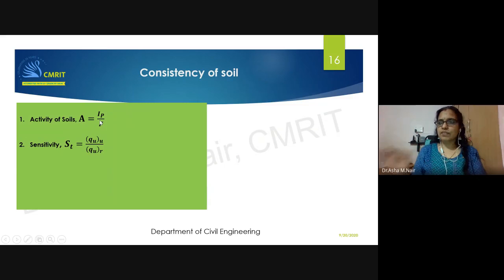Activity also, today we have done 2 problems based on activity. So please don't ignore these topics, because there is nothing so difficult in this, but please ensure that you are aware of all these things. So activity is equal to IP by F. And sensitivity also we have not seen, but I am telling you, you are going to get sensitivity based problems when you start with shear strength.